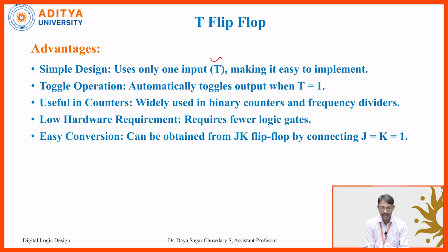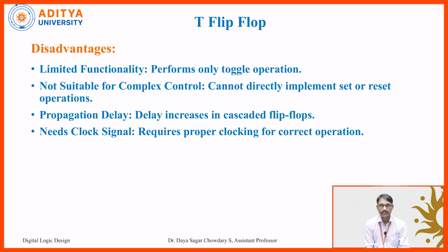And it has low hardware requirement, that means it requires few logic gates, and easy conversion can be obtained from the JK flip-flop by connecting the J and K input terminals directly together. Coming to the disadvantages, it has limited functionality, performing only the toggle operation, and is not suitable for complex control.